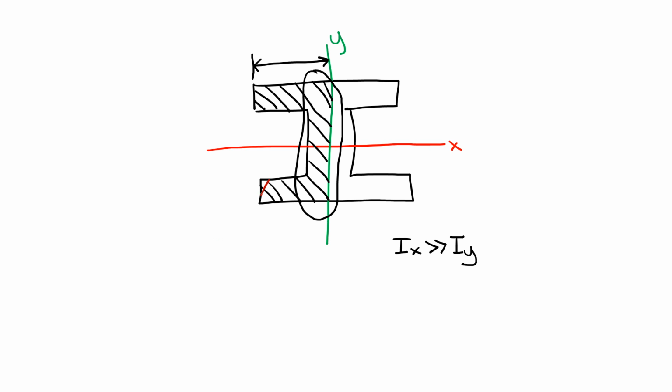When I look at my x-axis, the area that has to fold on top of my x-axis is all of this area instead. And therefore, this area is a very good distance away from my x-axis, which makes my moment of inertia in x much greater than my moment of inertia in y. For the purposes of the boat design competition, the area moment of inertia of the design waterplane is used to determine the boat's stability and the ease of the boat rotating through its pivot point.